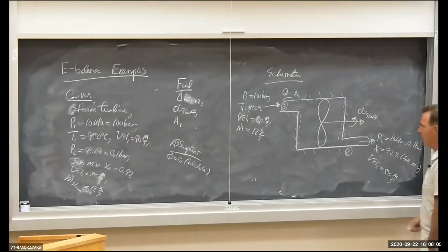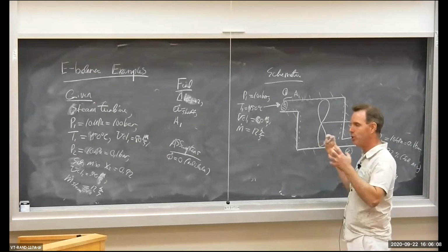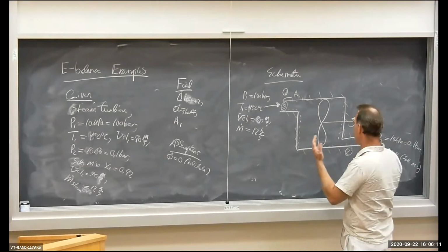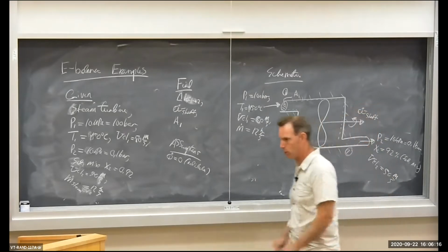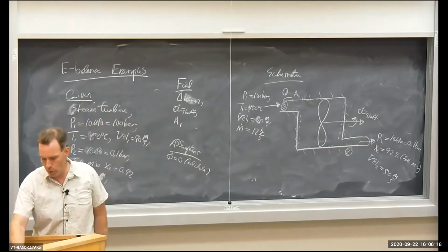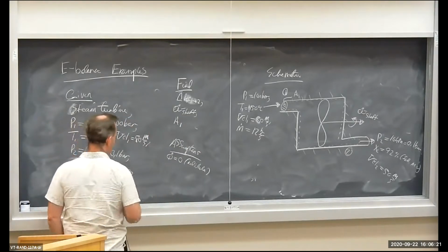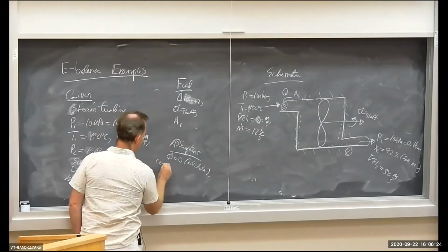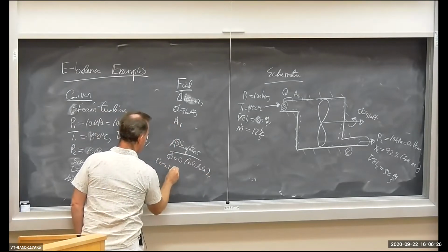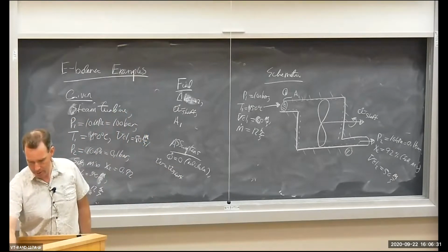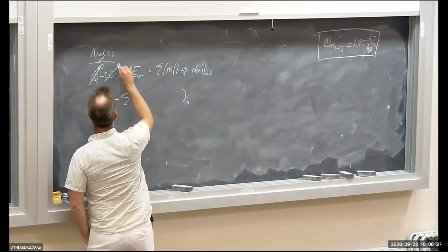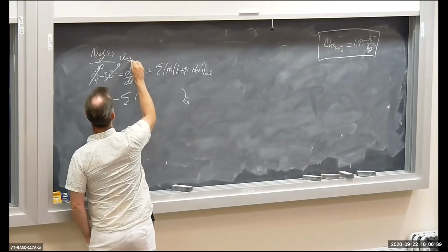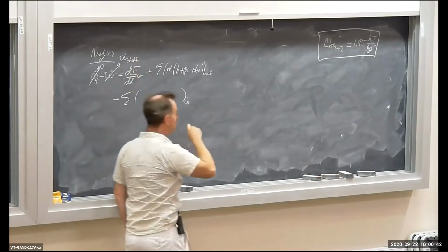And I'm assuming that the turbine itself is not changing shape. The casing is remaining intact, and the control volume is not changing its volume, getting bigger, or being distorted. So I'm going to assume that W dot is equal to W dot shaft. No boundary, no electric work. So I'm immediately going to substitute W dot shaft.